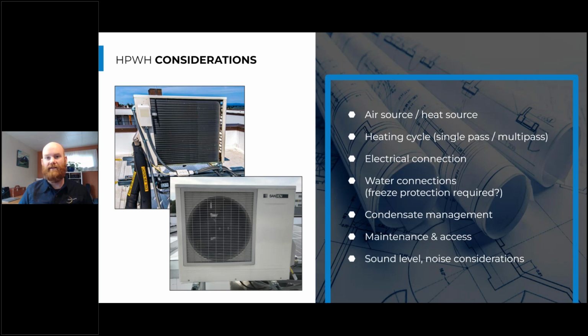So just understand what type of technology you're working with, and ask that manufacturer for their sound power levels. There are compressors and fans that spin, and those typically generate noise. So if we're putting these next to a residential window, it's probably not the best place. If we're putting them on a rooftop, we probably want some type of isolation from that roof, especially if it's a larger commercial piece of equipment that might shake a little bit during normal operation.